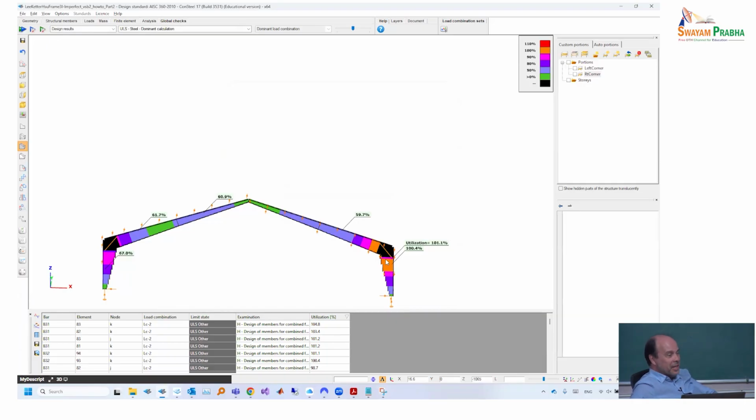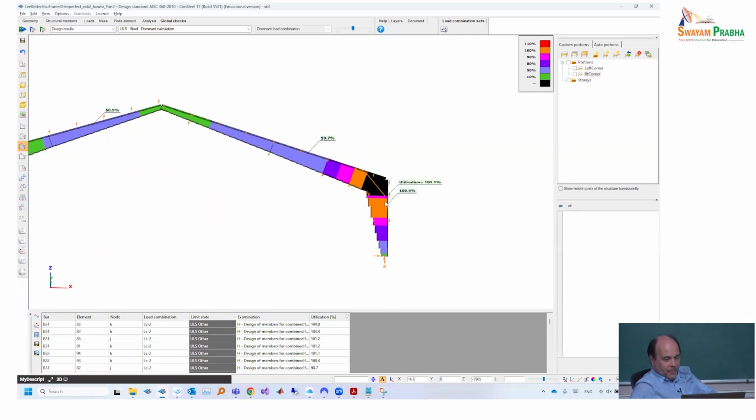So everything we do has an impact on the slenderness. We have improved the slenderness calculation, which improves the LTB strength calculation. But as long as the local buckling remains the controlling one, actually it makes no sense what we do. Flange local buckling, hint, hint, hint. What do you do about it? Okay. Now there is one other thing, and then we are at the end of this part of the demonstration, and then we can start to explain what the exercise will be.